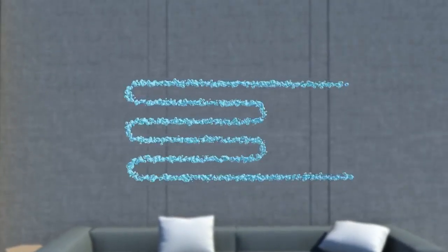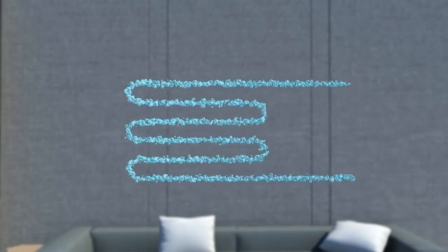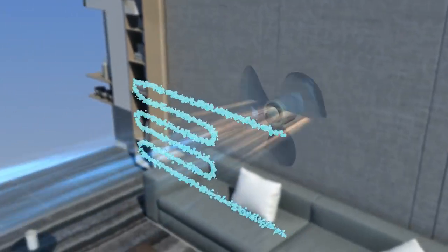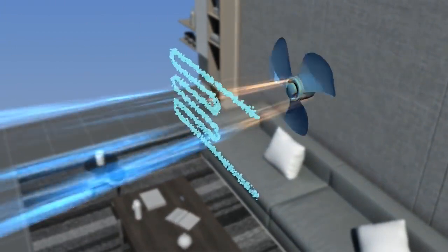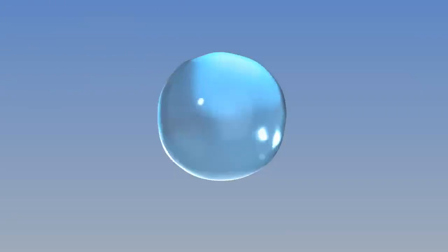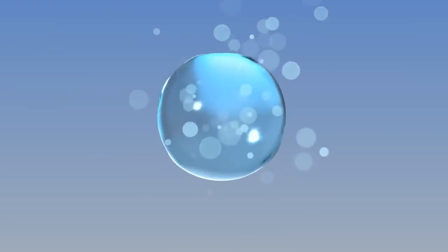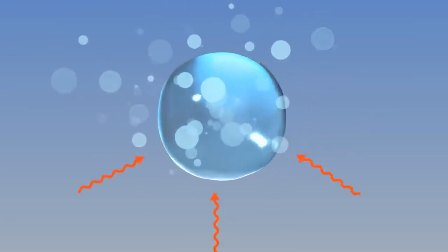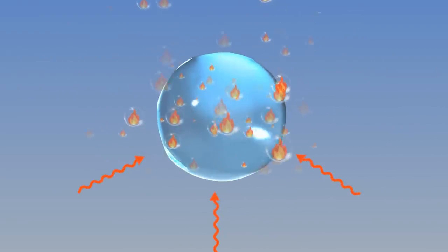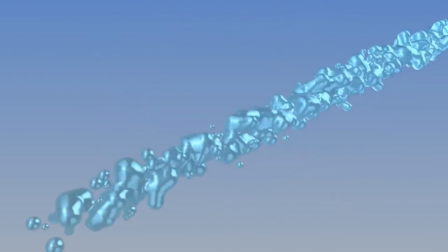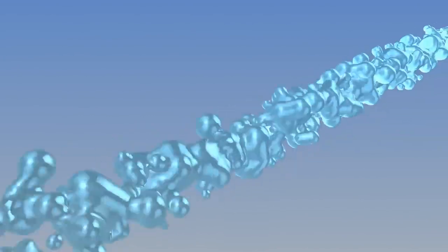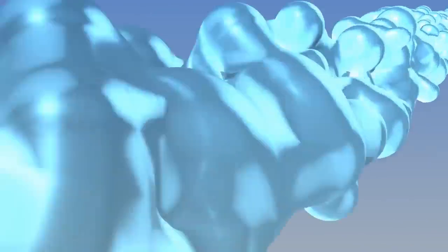When we blow wind from behind the refrigerant, air that lost heat becomes cooler and a cool breeze comes out from the front. The refrigerant used in an air conditioner tends to evaporate easily and has high latent heat of vaporization, which makes it perfect for a cooling device. Now, to understand how an air conditioner works, let's follow the flow of a refrigerant.